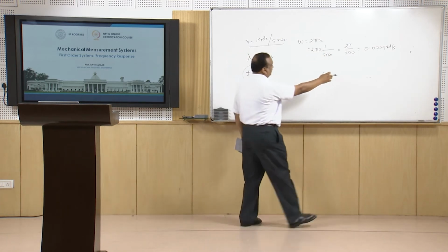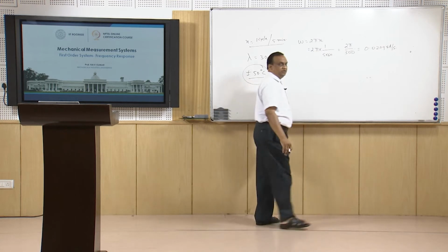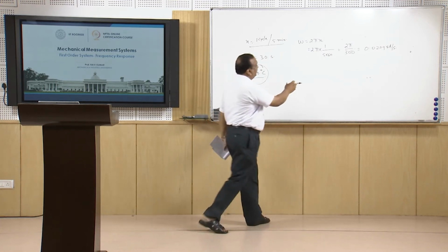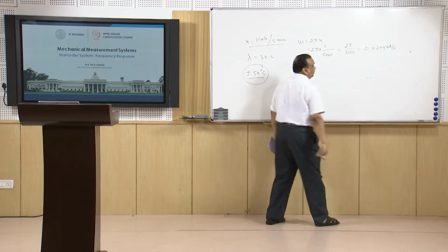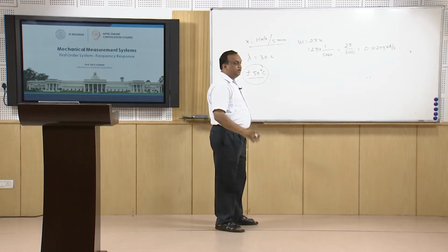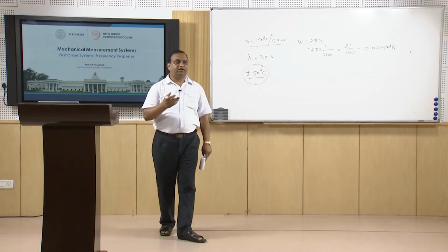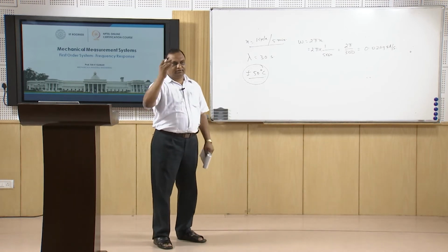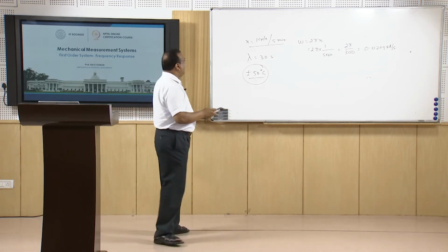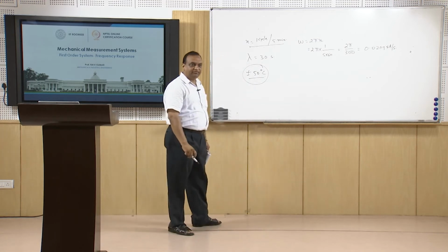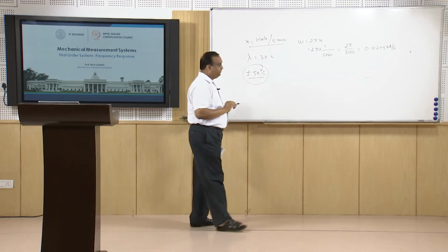This is frequency, or omega. The frequency is 1 cycle per 5 minutes and the value of omega is 0.0209. Now, the response of the temperature sensor. The temperature sensor will also have a sinusoidal response and the cycle time is again 1 cycle every 5 minutes. This is going to remain the same, but the amplitude will change.